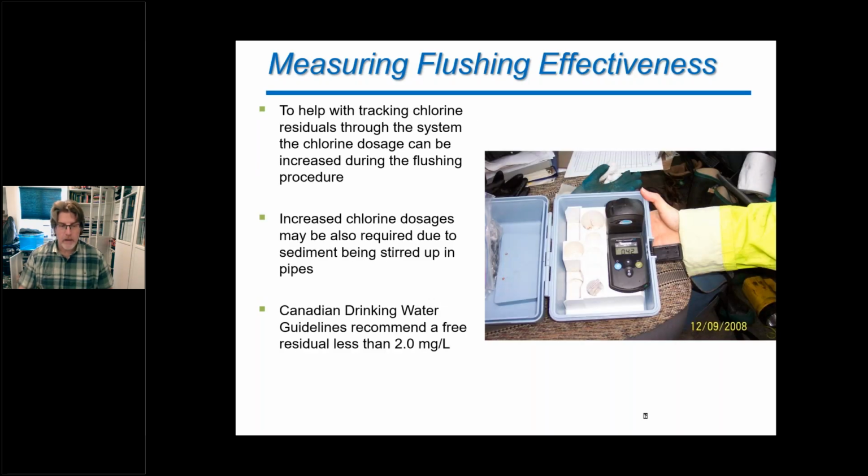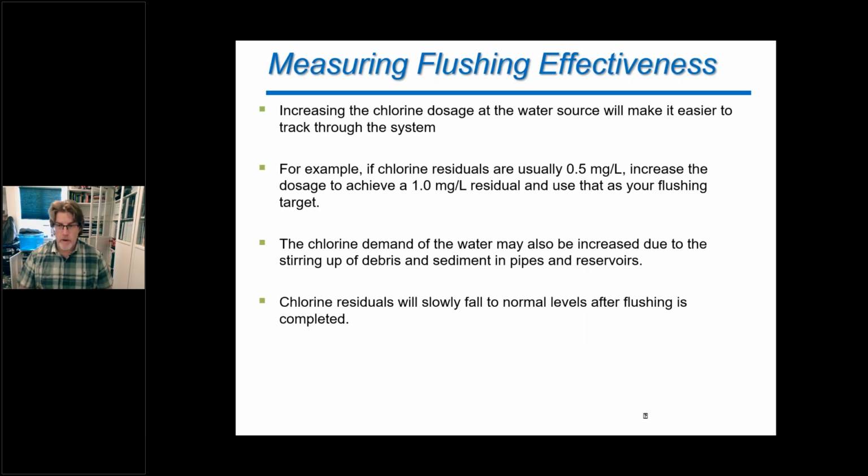Chlorine residuals. We want to look at what the chlorine residual was before I started flushing, what the chlorine residual was after I did my flushing, and did I see that chlorine residual rise? One of the things that is recommended while you're doing your flushing is to actually increase the chlorine dosage that you are putting into your system. And this makes measuring that new chlorine residual as it moves through your system very, very easy, especially if you don't usually have very much.